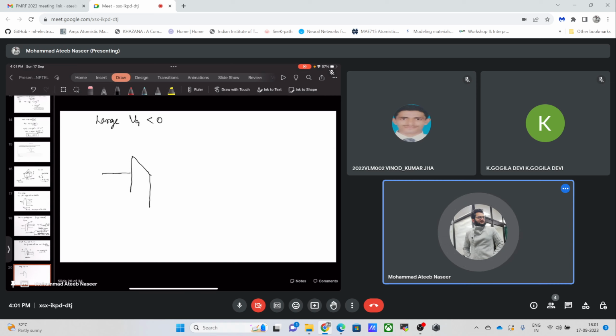Since Vg is very negative, the Fermi level on the metal side has gone up relative to the Fermi level on the semiconductor side. The semiconductor-side Fermi level remains constant throughout, but at the interface the intrinsic Fermi level will behave like this because of the charge buildup of positive carriers, and the interface becomes very much p-type.